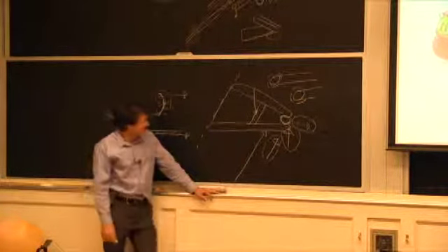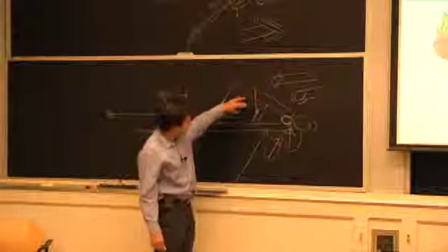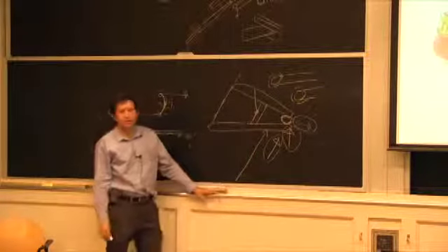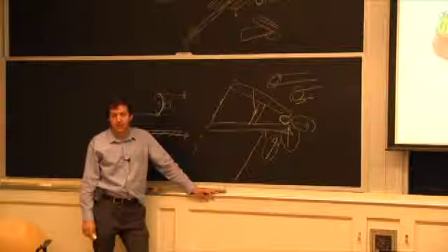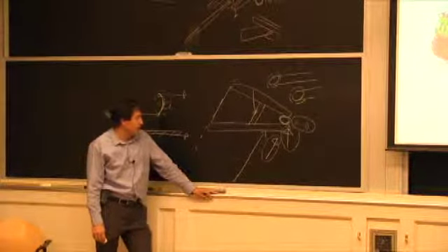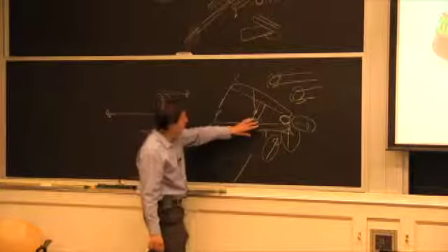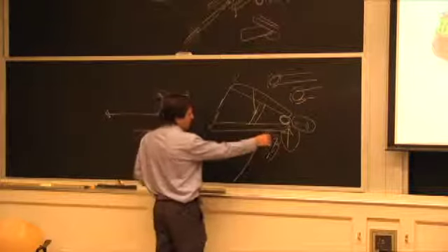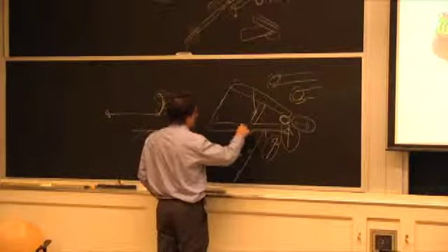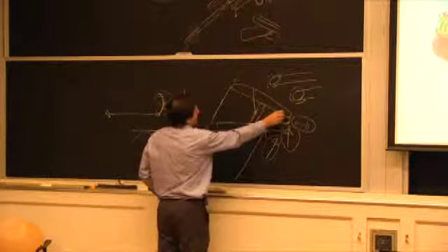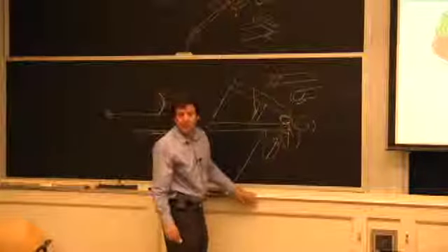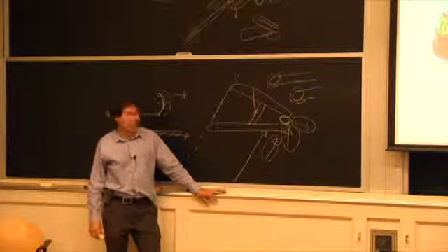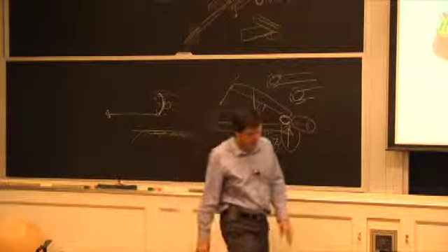And that's another thing we haven't really got into, each member, but they all have a very specific criteria that you have to design against. If you want to take the weakest point of this, it would be a competition between a weld that's too small here and maybe this member being a little bent to begin with, something like that.